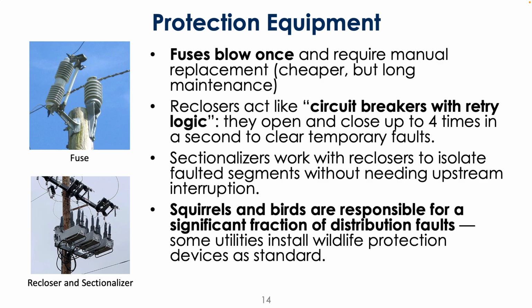But you might use something a little bit more sophisticated, such as a recloser. A recloser is kind of like a circuit breaker. It will open the circuit when you have some kind of fault that you want to deal with. Like a fuse, it's going to activate under certain conditions and open the circuit, but then it's going to try to close the circuit again to clear what might be termed a temporary fault, right?